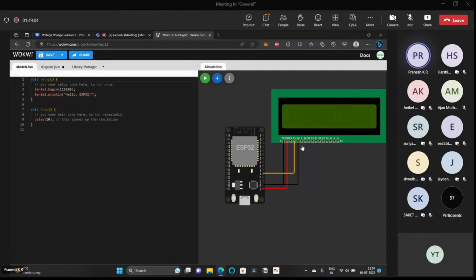And now let us come to enable. Same as register select, the enable pin controls the data transfer and synchronizes the timing of updates, ensuring communication between the microcontroller and the LCD. This enable pin helps the LCD display communicate with the ESP32. That's the main use of this enable pin. Similar to register select, we don't know how to use this, so the microcontroller will take care.